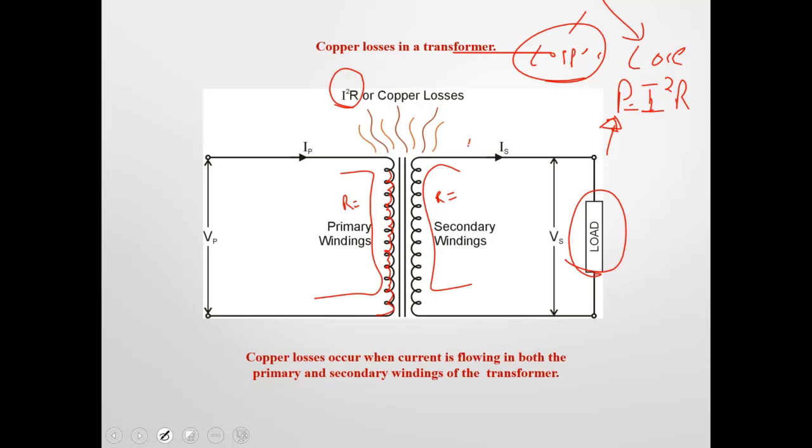And it is the actual current flowing through the windings, okay? It doesn't matter if it's in phase with voltage on the load or if it's out of phase. This could be an inductor or a capacitor, okay? If it draws 10 amps, that 10 amps is going to go through that winding. If this is a 2-to-1 transformer, it'd be 5 amps over here. That's what's going to flow through this winding, okay? That current must travel through this copper wire, and so it will always produce I squared R.